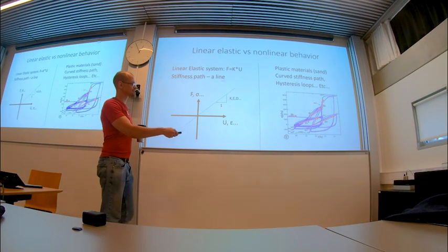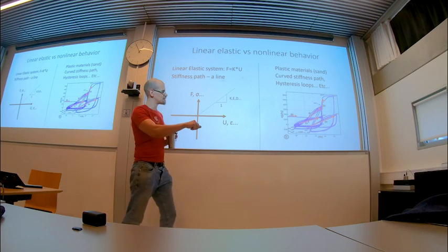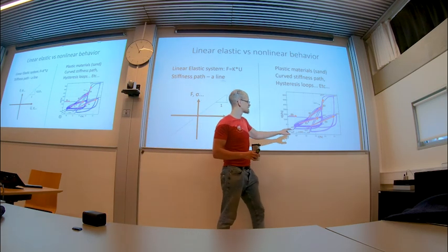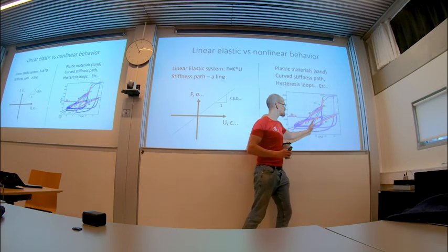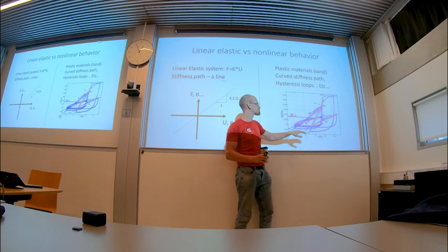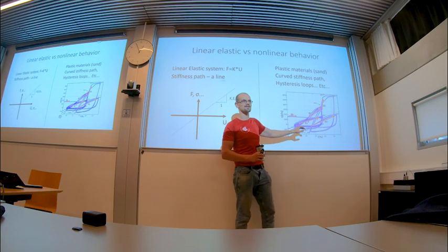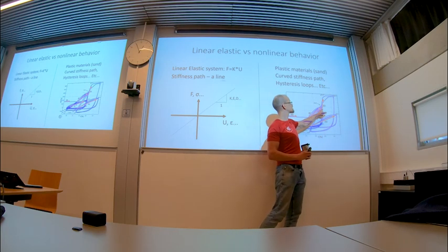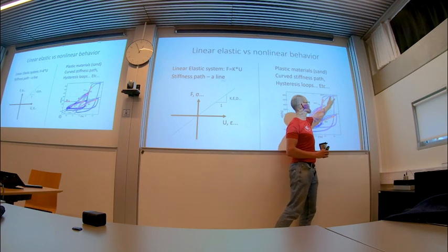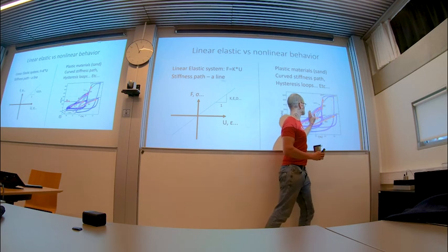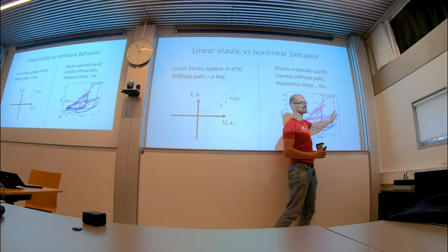And this is, by the way, a real test from a real triaxial simulation. And this is the thing I discovered, that if you apply the deformation of this size and keep doing it, the hysteresis loops have a constant shape. You increase the confining pressure, keep the same amplitude, the strength increases, the peak, but it doesn't really change the general shape. If you normalize it, it actually overlaps with the previous. And then you stop here, increase the confining pressure more, strength changes, and then change the amplitude too. And then now, after 2 cycles, the triangle is here, and then if I reduce the confining pressure, stopping around here, you have another triangle.